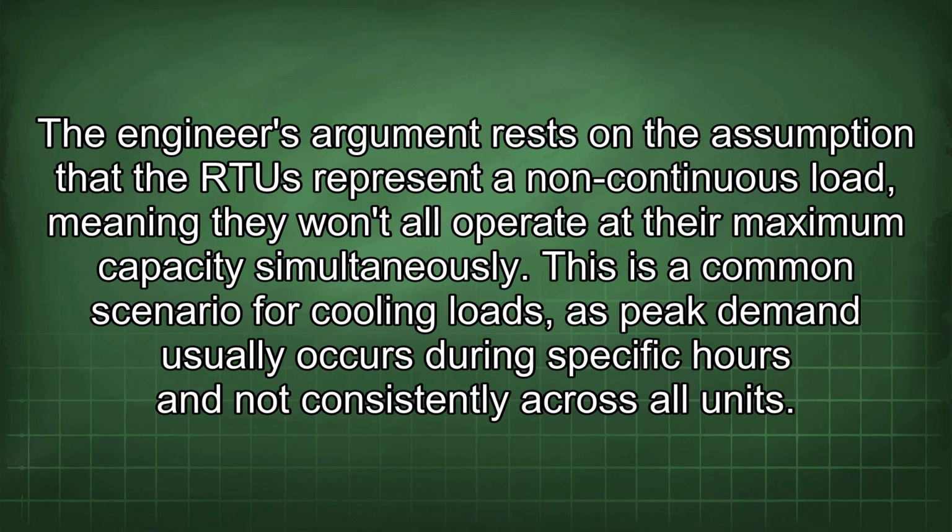The engineer's argument rests on the assumption that the RTU represent a non-continuous load, meaning they won't all operate to their maximum capacity simultaneously. This is a common scenario for cooling loads, as peak demand usually occurs during specific hours and not consistently across all units.